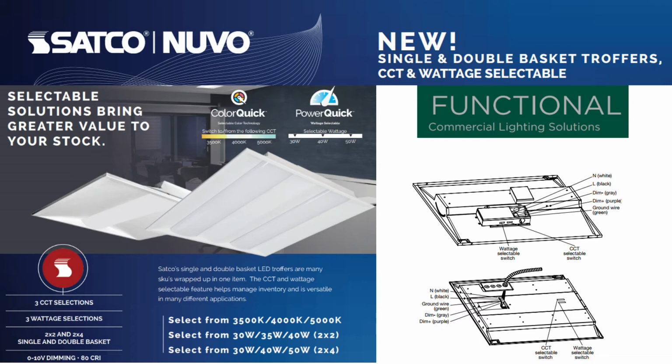For basketed lay-in, we have both single and double basket troffers or lay-ins. They feature color quick and power quick. 3 color temperatures selectable, 3500, 4000, and 5000, and power quick allows you to change the wattage from 30 watts, 40 watts, or 50 watts. So if you're doing a design with one of these fixtures, you need to select or decide which power you want, and then the design will be accurate.